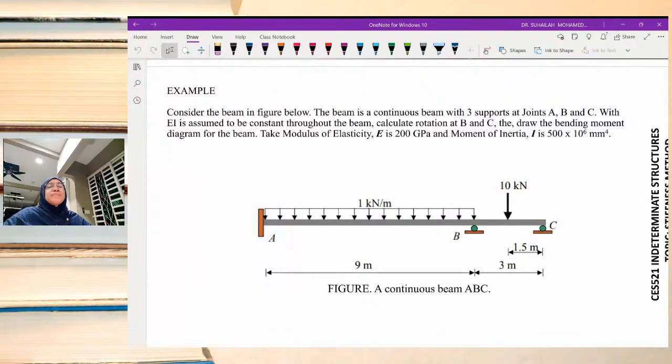In terms of degree of freedom, for truss we have to consider the degree of freedom per node in x and y direction, because there is no moment, there is no rotation in truss. In beam, we still have to consider 2 degrees of freedom, but this time in the y direction and z component.